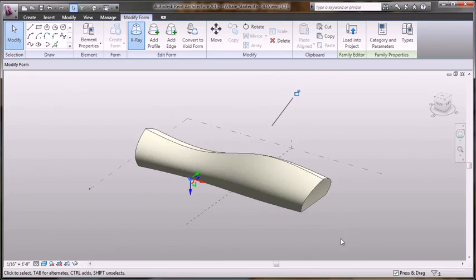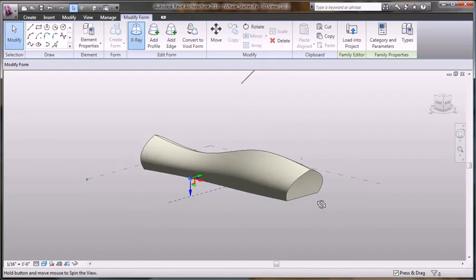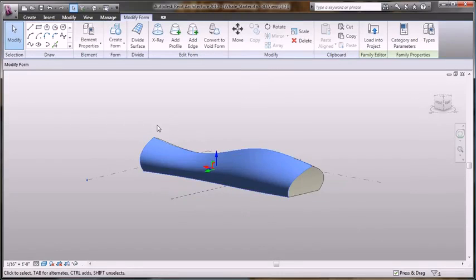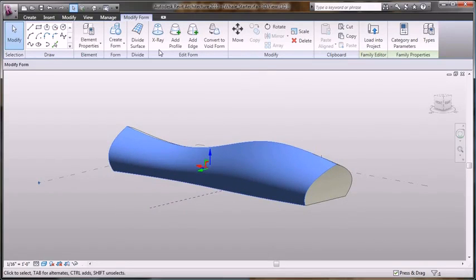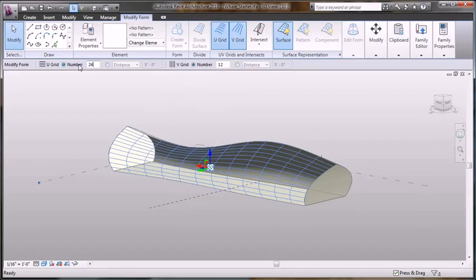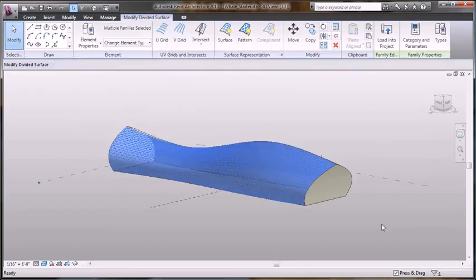So now that I have a form that I like, let's talk about how Revit Architecture can give us an even greater understanding of this design. This release comes with additional tools that will actually divide and pattern surfaces of the model in an effort to give us a better understanding of its scale. This pattern tool can be used at a very schematic level to illustrate curtain or structural systems, but this tool can be very precise as well, giving us the ability to apply real-world building components to them, such as a curtain panel.